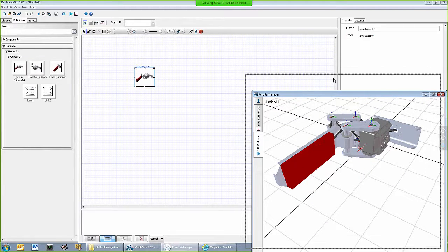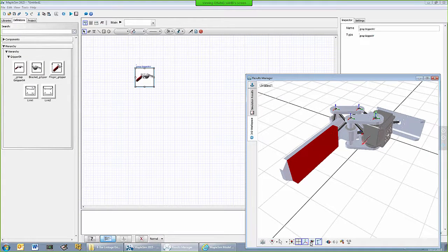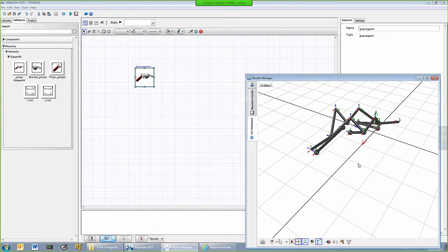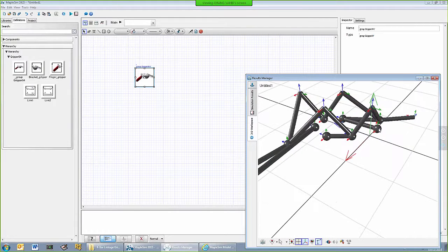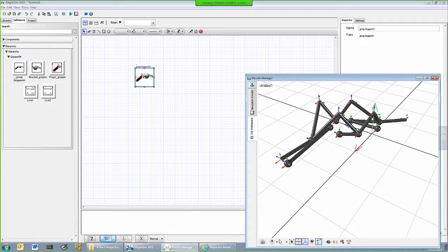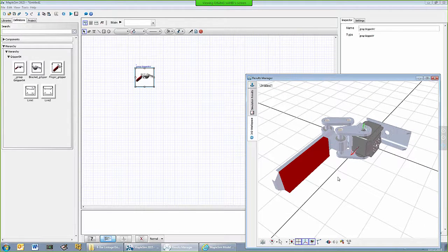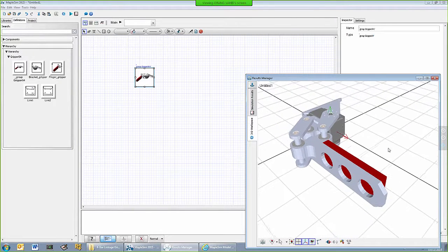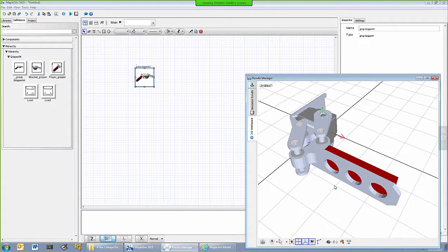So the component, if I just turn off the CAD view, I can see what actually is inside. This spherical visualization is where the mass and inertia is located, and the cylinders are the rigid body transforms or rigid body frames that enable different coordinates or frames that we just added in our import window. So let's switch to full CAD view. Now that we have this system at hand, we can go ahead and start adding the components, connections together.